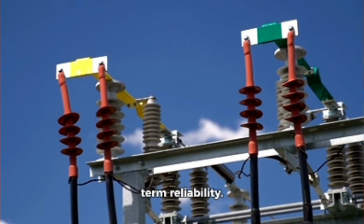Choosing the right MCCB is critical. You need one with a current rating that matches the total load of your distribution board. If the MCCB is too small, it will trip constantly, causing annoying power outages. Too large, and it won't provide adequate protection. Again, refer to those handy electrical codes and consult with a qualified electrician. They'll help you choose an MCCB that's just right for your office's electrical needs.